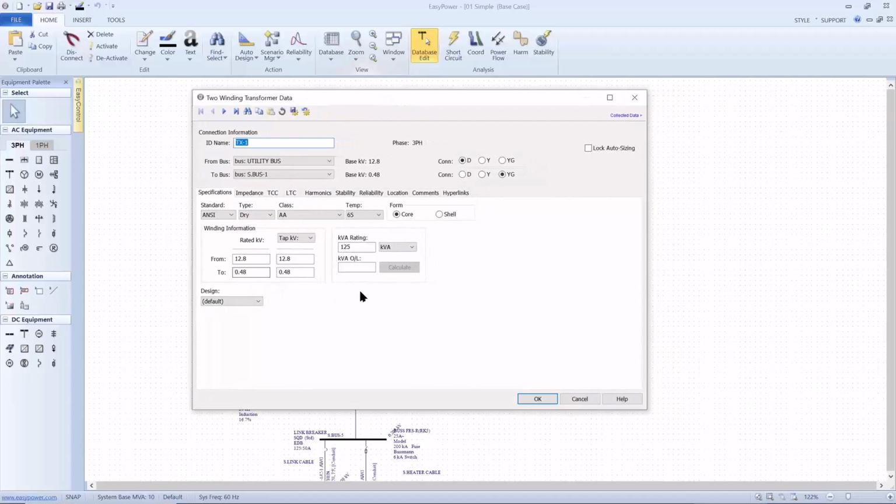you'll notice that all the dialog boxes have the same general format: unique identifier, the connection point in the system, and a number of tabs. The ID name has to be unique for that generic type of equipment. If you have a very large plant, you may need to come up with a unique labeling system that gives you some designation, either to the load or the substation, that identifies this part and can be found easier, frankly, even with the database browser sorting for that particular subsection.